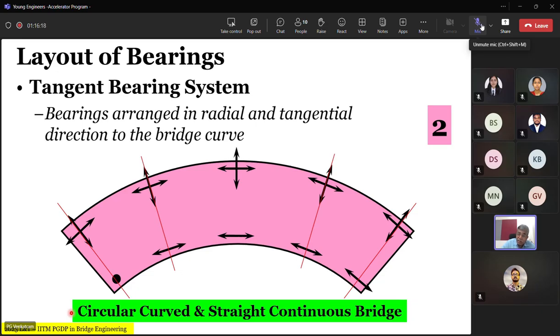So if you have a sharp radius of curvature, that means if the radius of curvature is small, then quite often you will find that the net forces, not design forces, on both substructure and foundation may be less if you go for polar radiating arrangement. But if you go for small radius of curvature, possibly the total length of the bridge also will be small. It's rare for a long bridge to continue on a sharp radius of curvature.